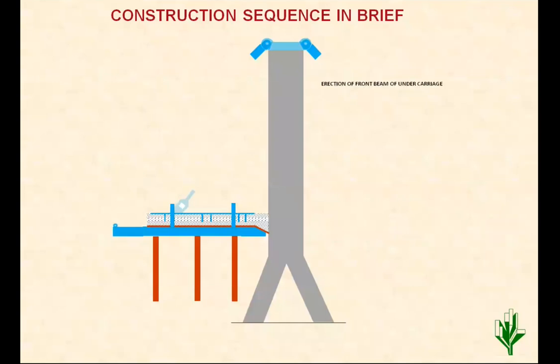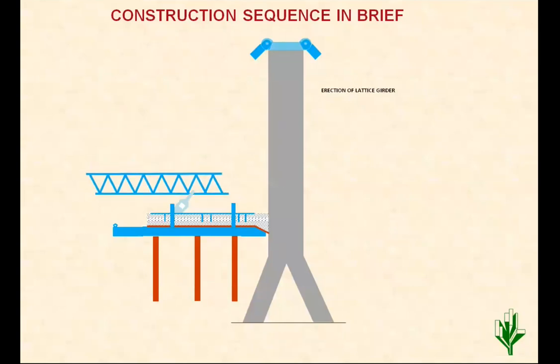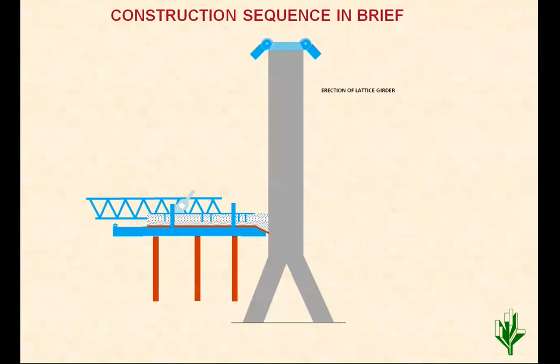Now some additional shuttering part is also connected further. Then on the top of the completed deck, one truss type erection crane is erected. There is a connection made between the bottom beam and the top truss. Then the first cable is traced.